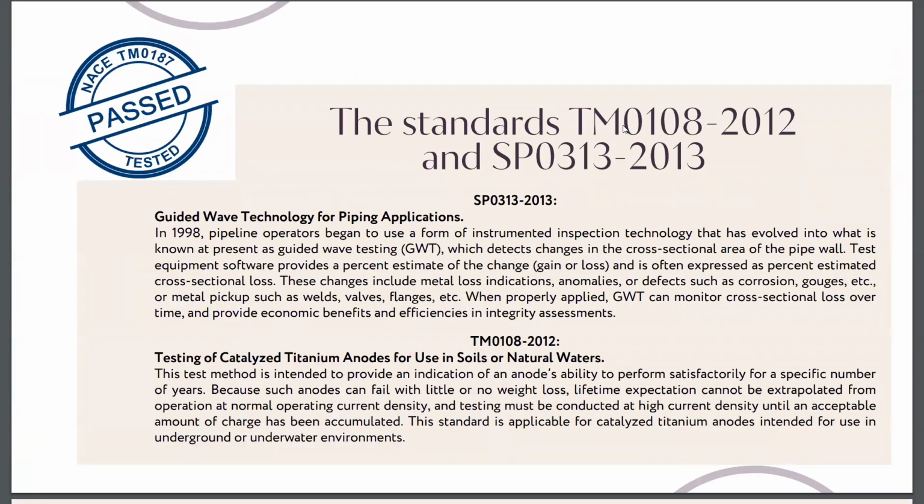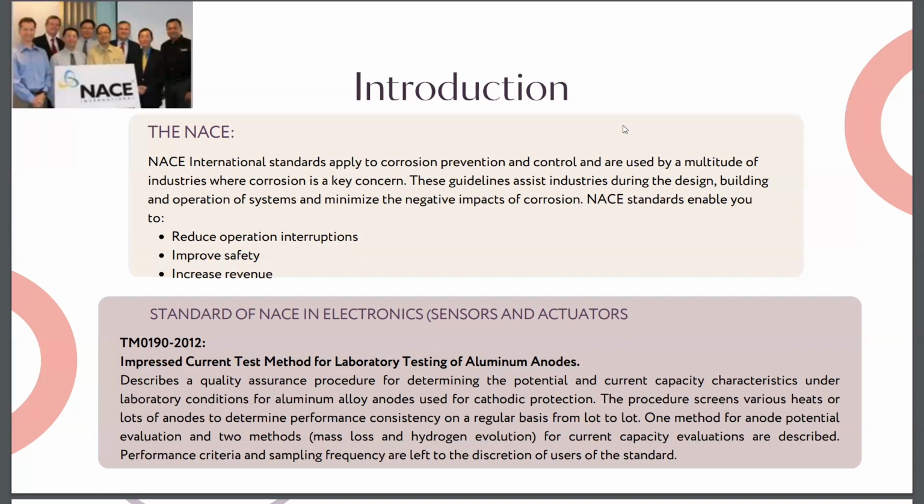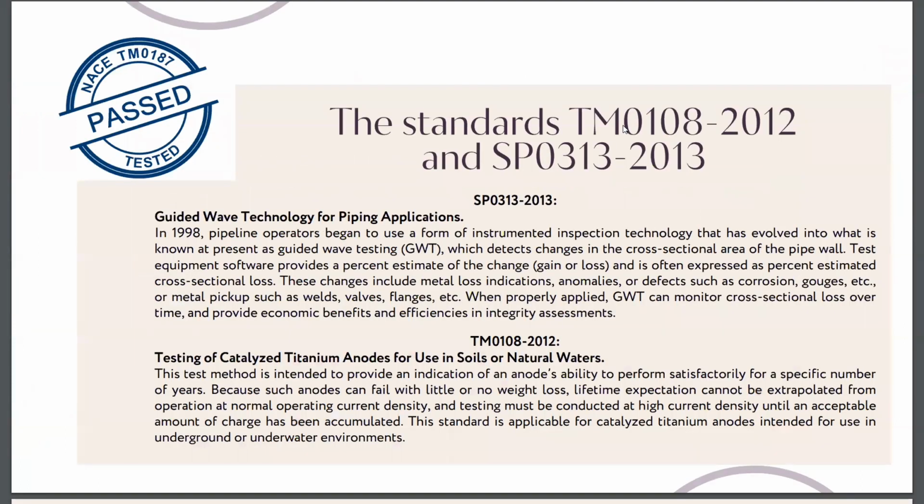The next standard of NACE is guided wave technology for piping applications. In 1998, pipeline operators began to use a form of instrumented inspection technology that has evolved into what is known at present as guided wave testing (GWT), which detects changes in the cross-sectional area of the pipe wall.